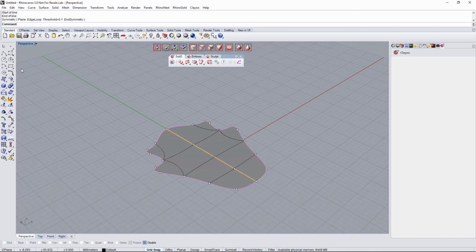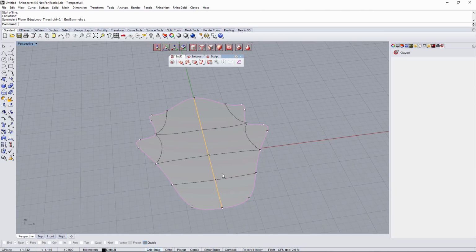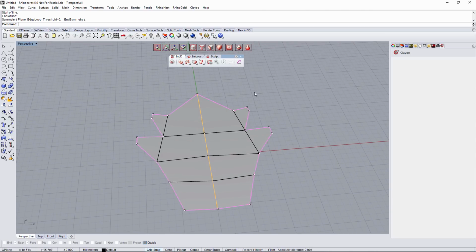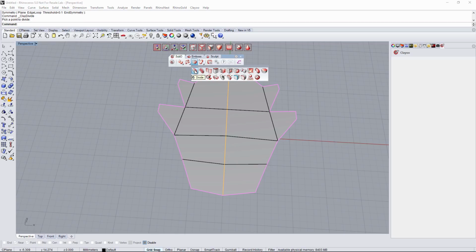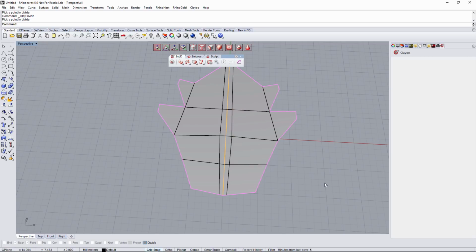So right now what I'm gonna do is create a detail here on the inside part. To do that, I'm gonna go back to this view, and I will use the insert tool. Sorry, no, the divide tool. I'll go to addition and divide, and I will create one more division line in here. As I'm in vertex selection mode, I'll have to go point by point. I'll select any other, and I'll go directly for divide, and I'll display this green line in here. So I'll go for a line maybe in here, perfect.